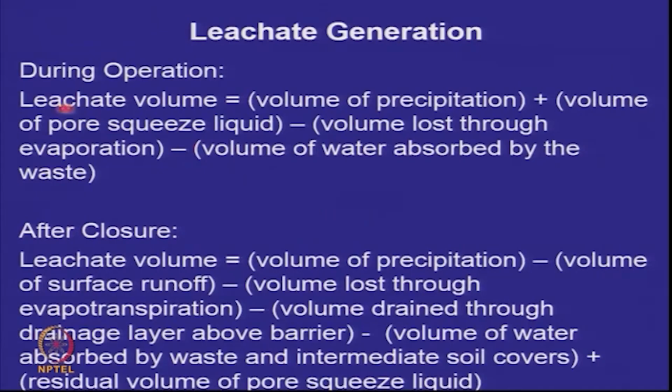So let me again put this: during operation, leachate volume is equal to volume of precipitation plus volume of pore squeeze liquid minus volume lost through evaporation minus volume of water absorbed by the waste. So please understand, there is no surface runoff presumed in this equation.